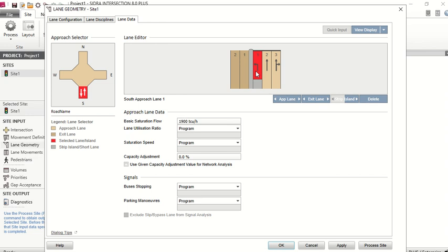Yes. What is TCU? TCU is through car units per hour. Saturation flow rate by default is for through. Now through means what? Straight. And cars. So it's already converted. Now when you put your volume, you don't have to worry about these things. The software will do the conversions for you because you are putting the data: percentage of heavy vehicles, the terrain, the gradient. So the software will do it for you.